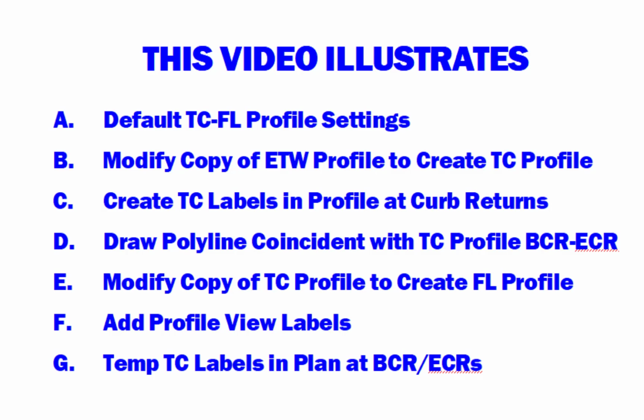D. Draw polyline coincident with top of curb profile from BCR to ECR within blocks. E. Modify copy of top of curb profile to create flow line profile. F. Add profile view labels. And G. Temporary top of curb labels in plan at BCR-ECRs.